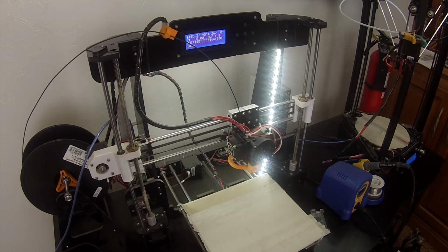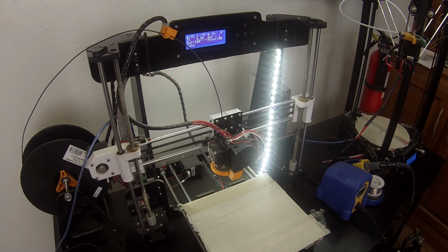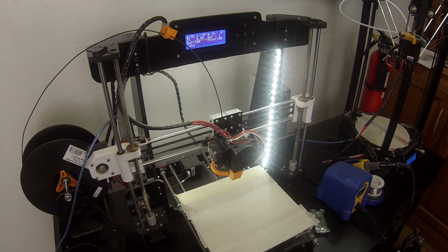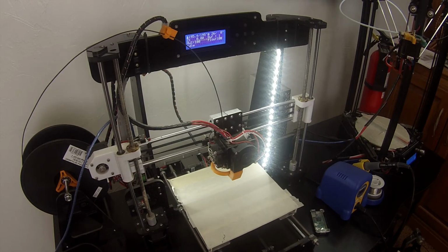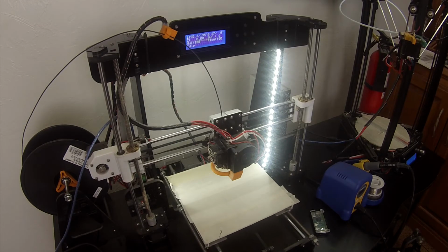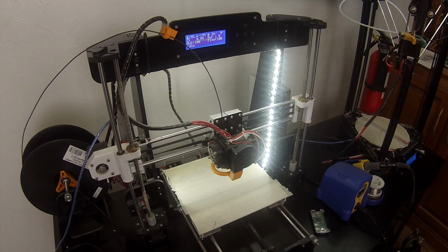At this point, you can move the printer if you want. Move it left and right. You can move the print bed itself. You can see that's just sending signals to the stepper motors. It's sending Gcode commands across Wi-Fi through the web-based interface to the Raspberry Pi. The Raspberry Pi interprets that as it's running the software, sends it out through serial to the printer. The printer then says, oh, I just got a command that says move the x-axis 10 millimeters. It translates that to a number of steps. It needs to move the stepper motor, and then off the bed goes. Really, to us, click the button, things happen.